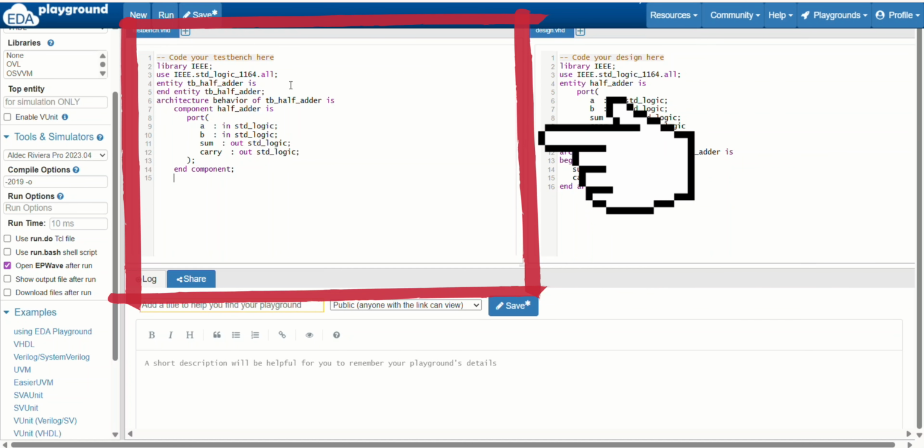Okay, so signal TBA. Here we are taking TBA because we are doing the test bench, not the design part. Okay, so we have taken the component as the design part, but the whole thing will happen in the test bench, because test bench is like testing your design, testing your hardware. Okay, so TBA, we have taken a new name. TBA means test bench A. You can take any name. Okay, std_logic, then colon equals, it is like equals only, but here the operator will be different.